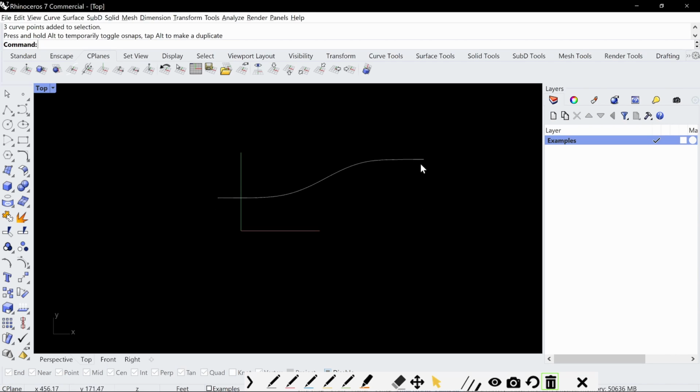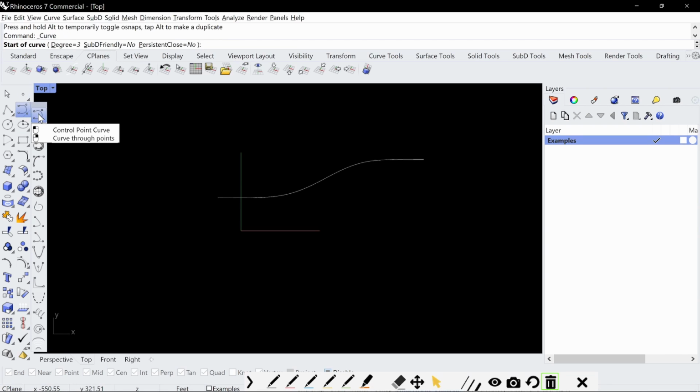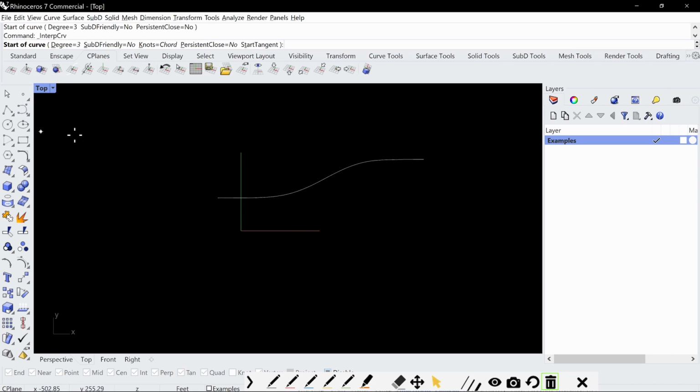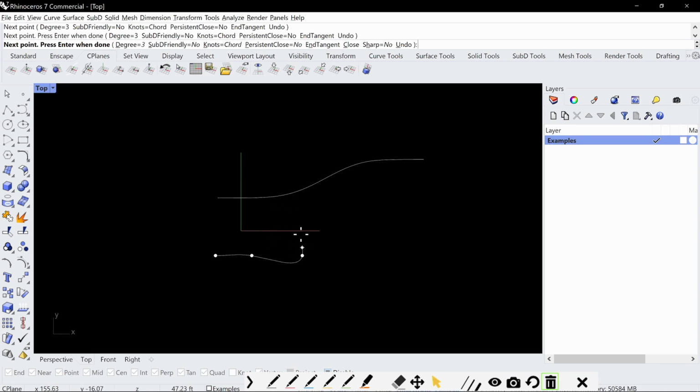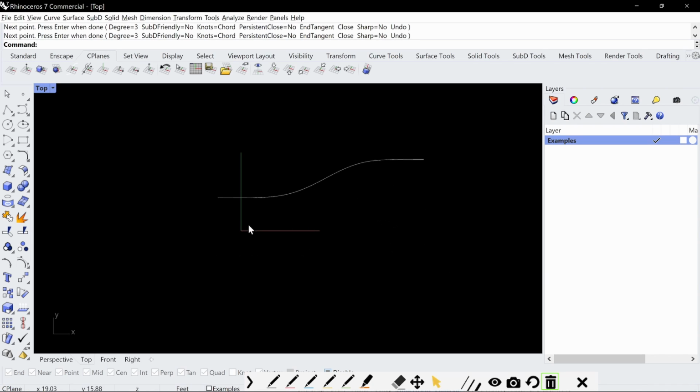It's a very organic way where I did curve, control point curve. I can do curve interpolate points, and it'll be the same thing, but I just want to show you the difference. You see how things start to bend right away? And so that's curve interpolate points. Sometimes this comes in handy when you have a lot of sharp curves that you want to follow.